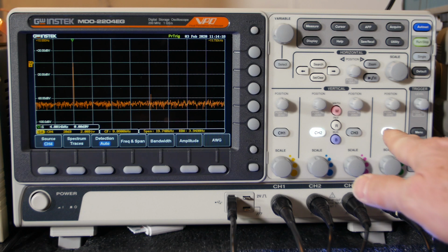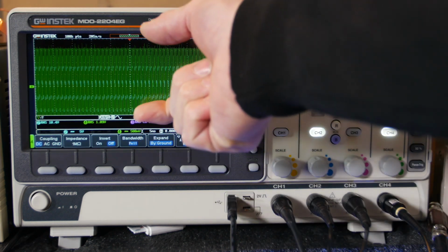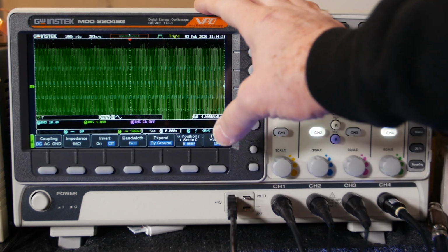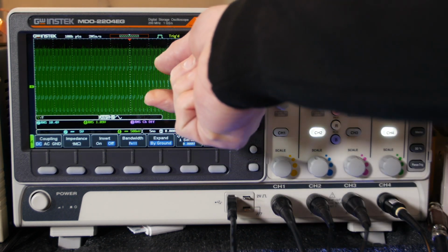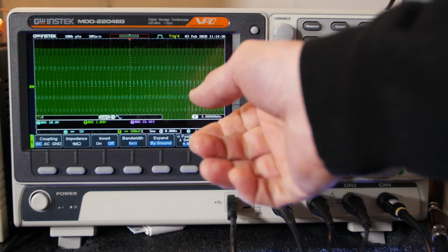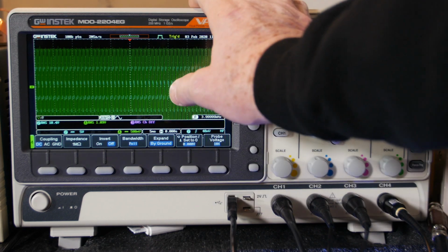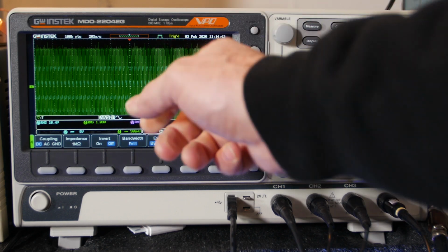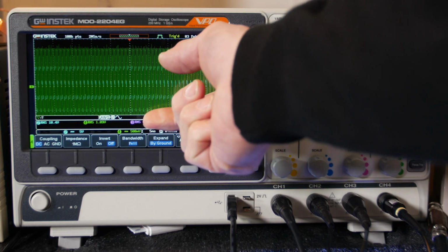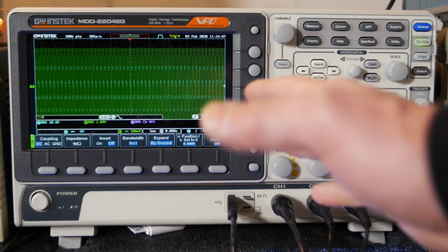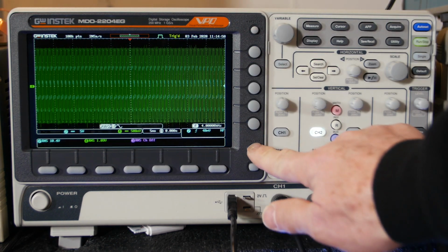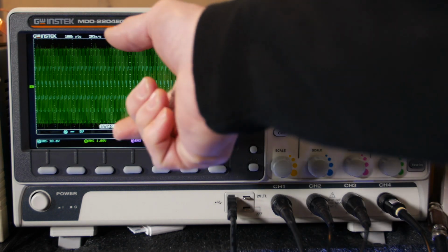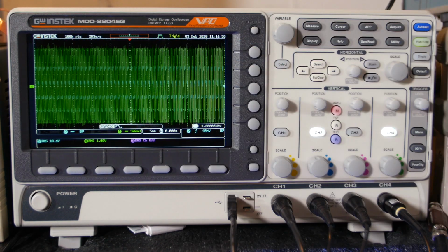Let me explain something real quick about the scopes. If you have an 8-bit A to D processor, you know, analog to digital, and you're only using part of the screen, you're losing bits. I think if you're down half the screen, you're down at 6 bits, which is huge. And if you're 3/4 screen, it's like 7 bits, something like that. I have to check that, look it up again, but I just kind of remember something like that. So anyway, whenever you look at the signals, you want the best resolution, so blow them up.